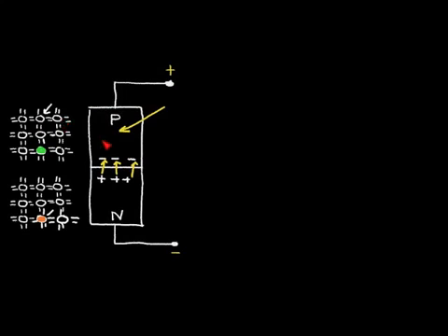And these electrons and holes can move around. And if, for example, a hole moves over into this region of the electric field, this hole will be pushed away towards the positive region. But if an electron enters this electric field region from the P region, this electron will be pushed down by this electric field, and it'll be pushed into the N region.